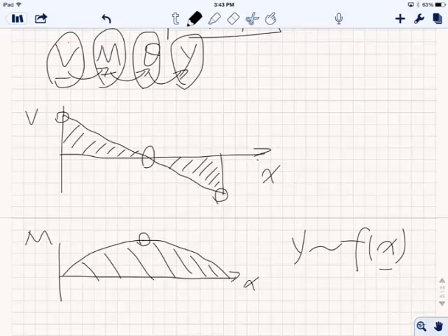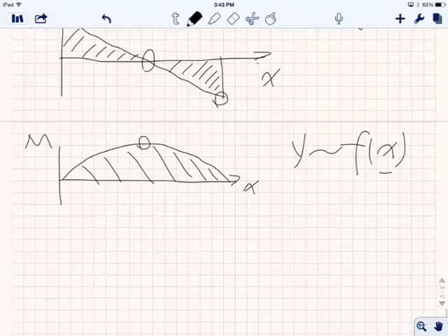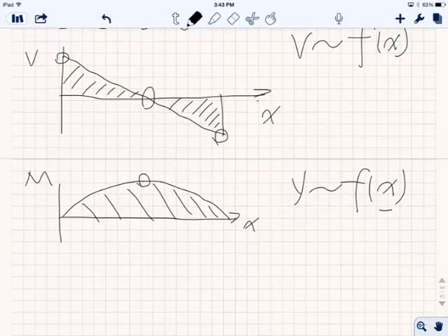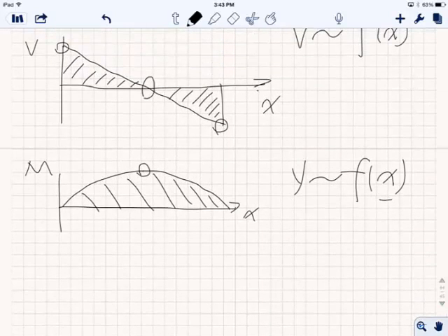So in other words, the first step will be we need to find out this, right? We need to find out at every single point what is the shear force. Therefore, once you do the integration, you'll know every single point of M, and at the end, you know every single point of the deflection y. Make sense? Yes? Confused? Yeah. All right. Okay, so let's continue over here. These two I don't have to explain, right? You already know what's going on here and here.